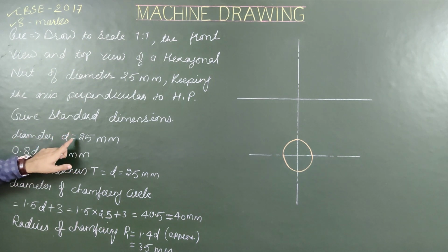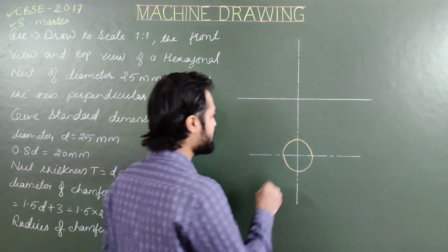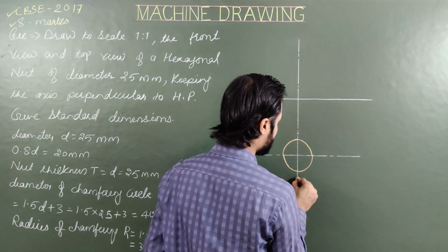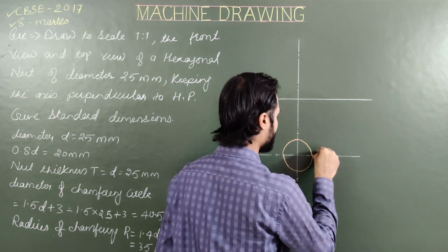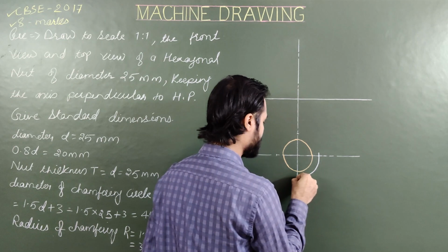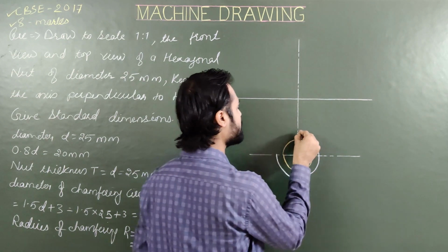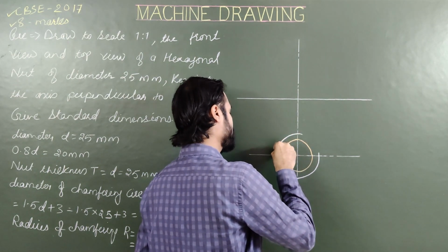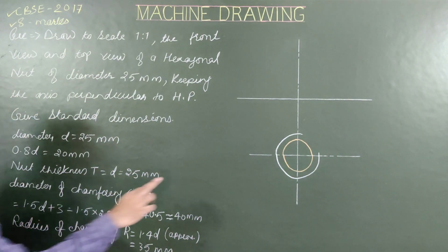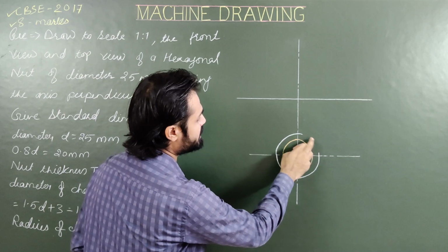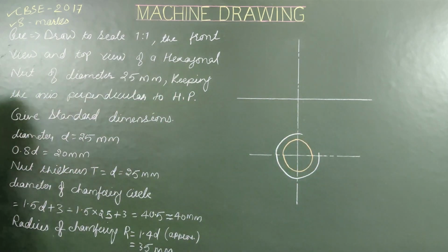Then second circle with diameter 25 mm, incomplete and medium dark. So please use an H pencil, and it's a medium dark circle. Also, the discontinuity will be in the first quadrant because we are using the first angle projection method.